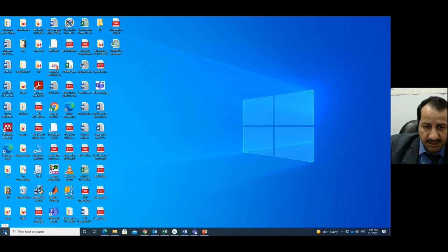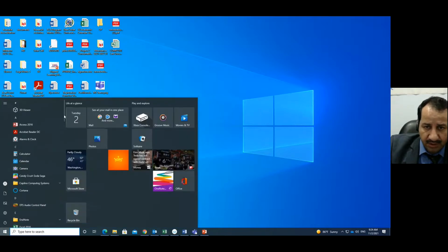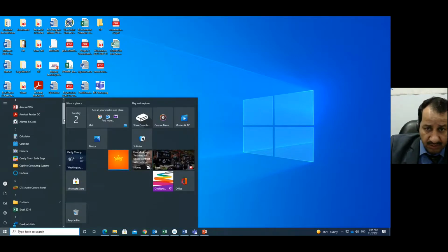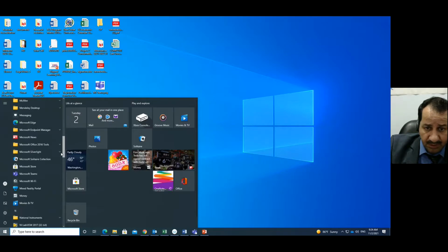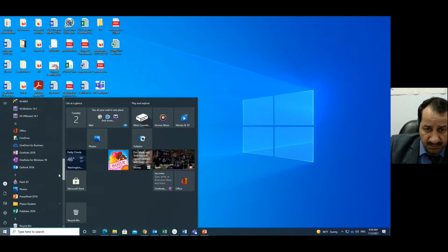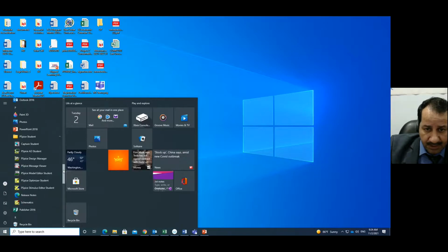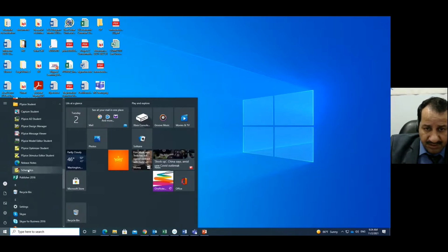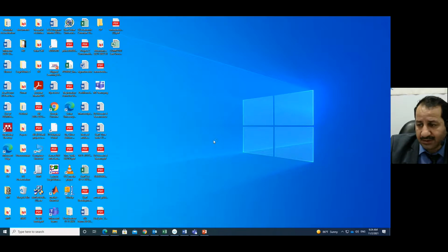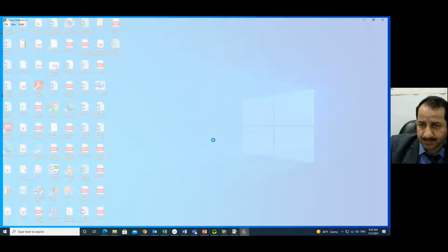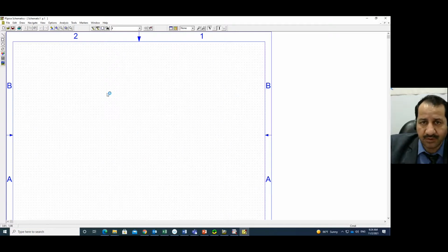now. I'm sharing my screen here. It's already installed on my computer, PSpice. I go searching for PSpice here. Where is it? This is it, click. I go for schematic. I open the schematic. Okay, you can see this is my window now.